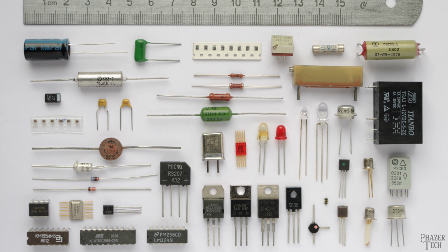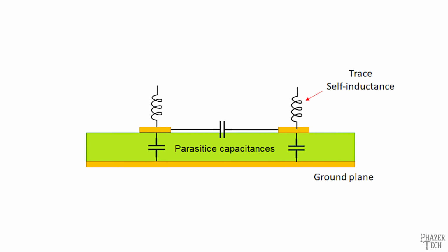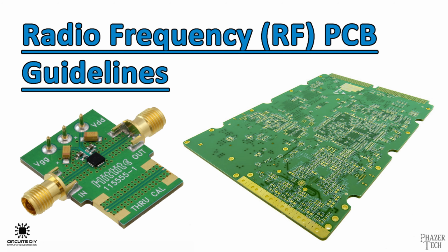The same concept applies to capacitors, inductors, transistors, and every other component. In addition to this, copper wires and traces in a circuit board also aren't perfect. And not only do they contain a small resistance, but they also contain some level of capacitance and inductance as well. In certain applications, this can be a big problem. For example, when dealing with high-frequency signals, let's say in the gigahertz range, special attention needs to be taken when designing a PCB and its traces in order to minimize stray capacitance, inductance, and other undesirable qualities.